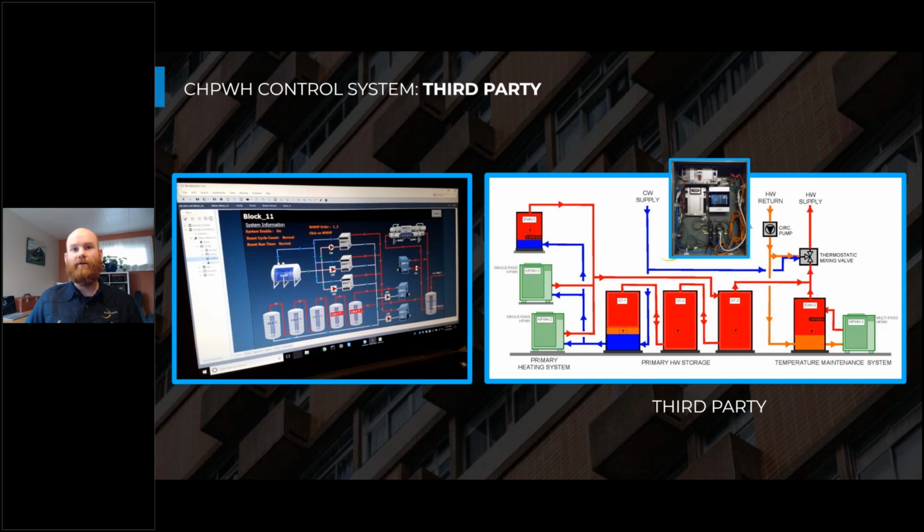And that has a water source heat recovery system where we're actually using the heat from the wastewater in the plumbing system to provide domestic hot water to the building. So there's a sewage vault that we're extracting heat from, which sounds crazy, but it works fairly well. It's definitely more complicated than our air source heat pump systems, but there's a lot of heat in that wastewater, and we can extract that and put it into domestic water for domestic applications at a relatively high efficiency.